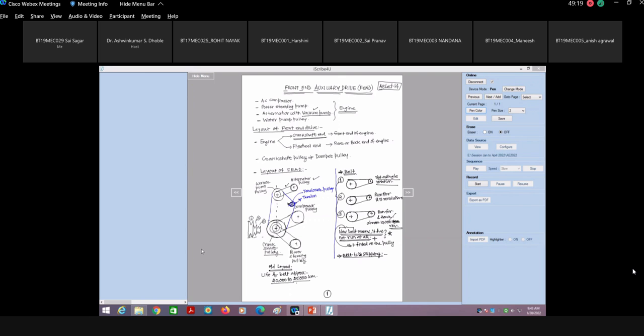Suppose you have to check whether there is slip of the belt on the pulley. So how do you identify that the belt is slipping now, or how? You have studied slip, you know it is the difference between the, what is the definition of slip, sir? Percentage slip and all. You have said that 3% is acceptable on the V belt. Am I correct or not?